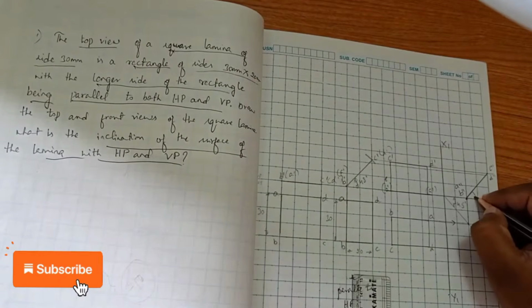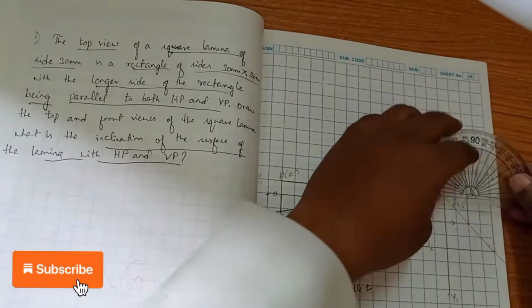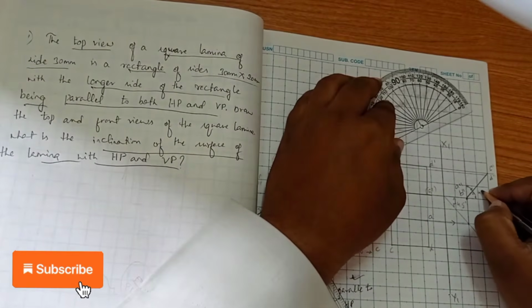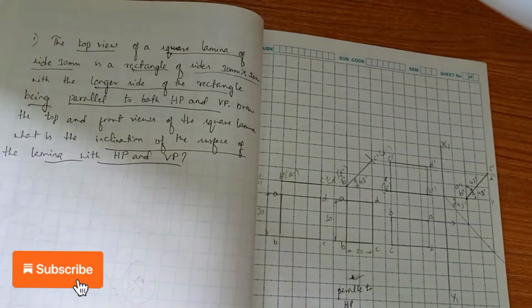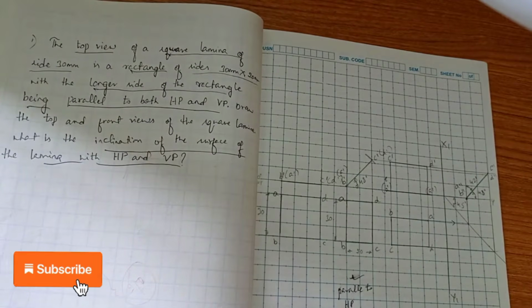Now we can find this angle of inclination to HP, and this angle of inclination to VP. If you measure it, we already have 48 degrees, so this is 42 degrees. 48 plus 42 means 90 degrees. So this is how we completed the problem. It was parallel to HP here, now it is parallel to VP. That's how we proceed in this problem.